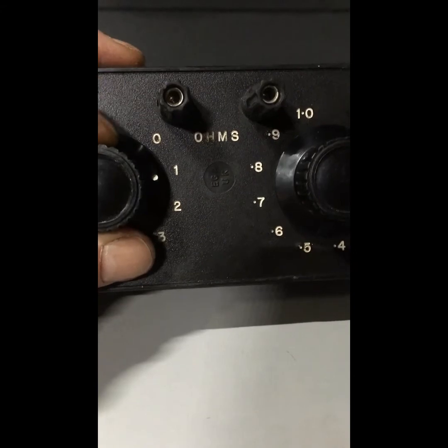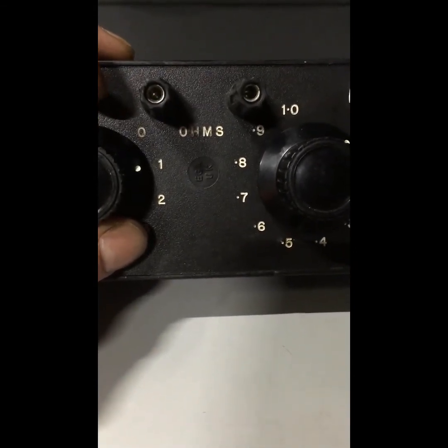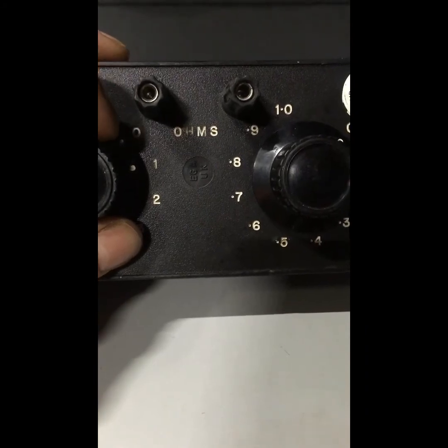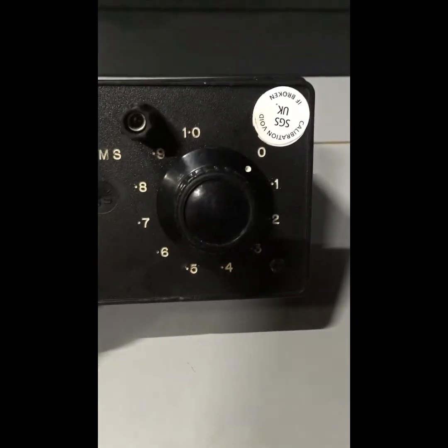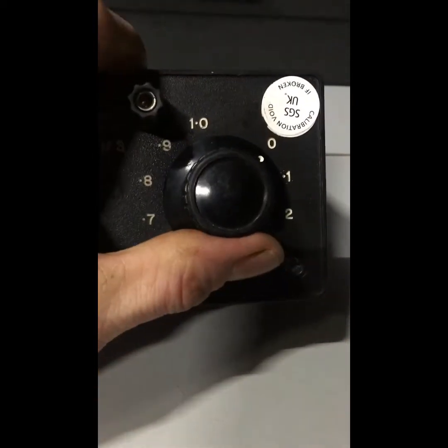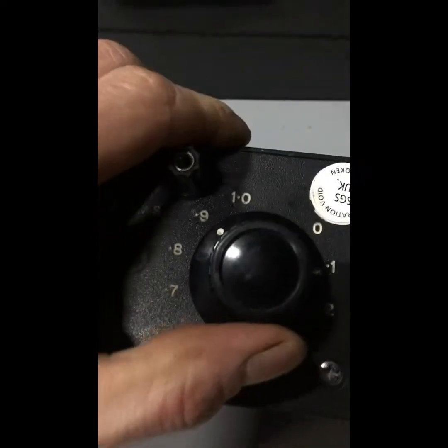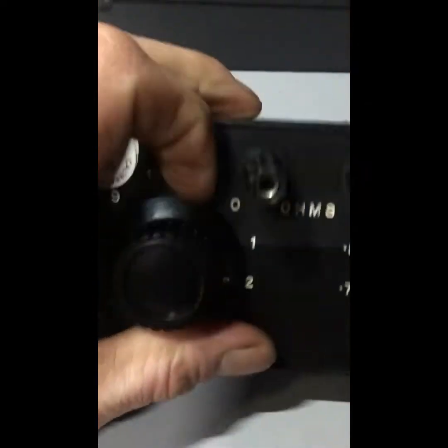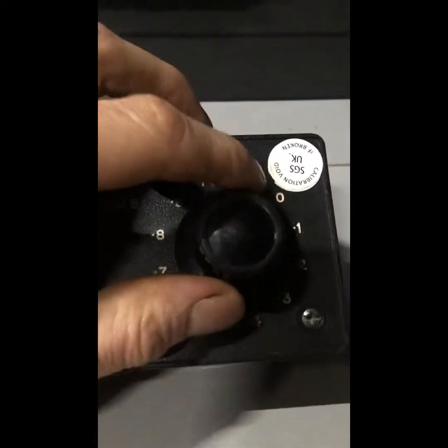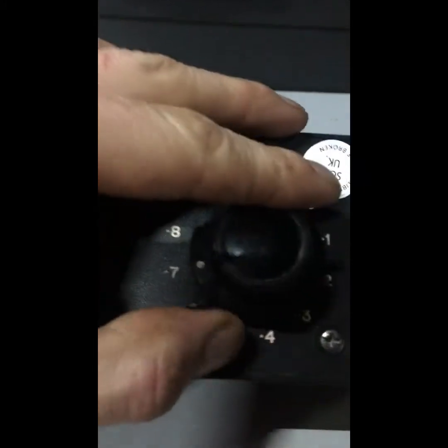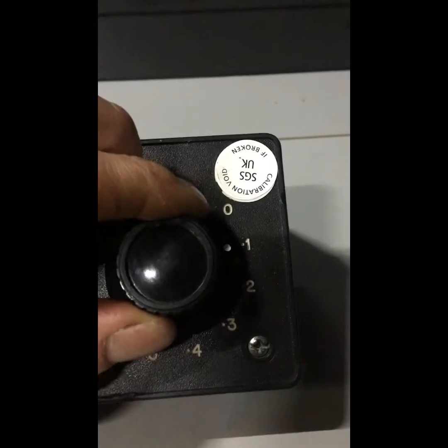And when we're shunting, we attach these leads to the rails at the relay end, and we observe the relay slowly start to drop. So if we were to start at, let's say, 2 ohms, so that's 2 and 0.0, we would take the tenths down all the way from here. So actually that is now 3, so we'll go down to 1. Plus 1 is 2, and we'll start slowly decreasing it. 0.9, 0.8, 0.7, 0.6, 0.5, 0.4, 0.3, 0.2, 0.1, 0.0.